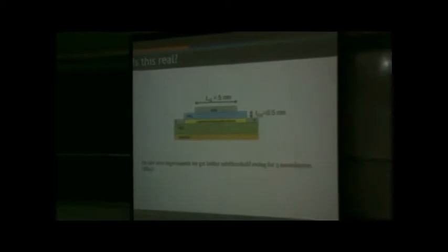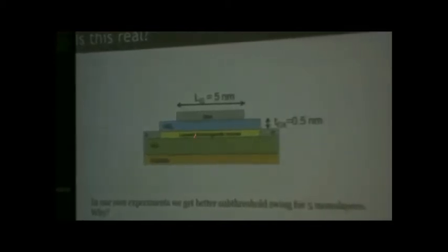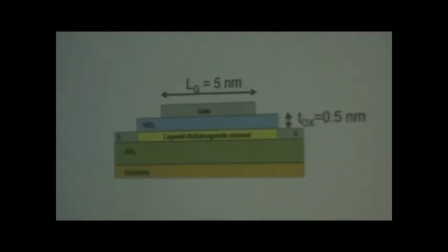The reason is very simple. The thing is, all our contacts are very bad. Okay, so we cannot push as many electrons as the layers can take. So what we see is once the device turns on, the topmost layer goes to very close to what you can get for 0.5 nanometers. So it is very far away from the quantum capacitance limit because of the very high density of states. As a result, it totally screens out your gate electric field. So therefore, the layers at the bottom do not even see it. So it just acts like a dielectric layer sitting there.